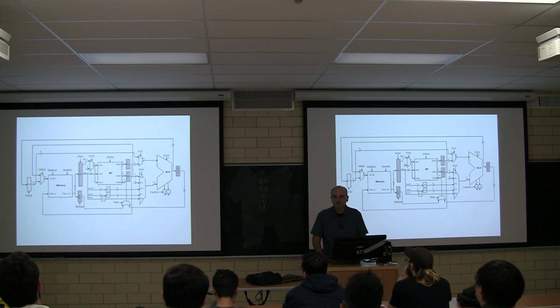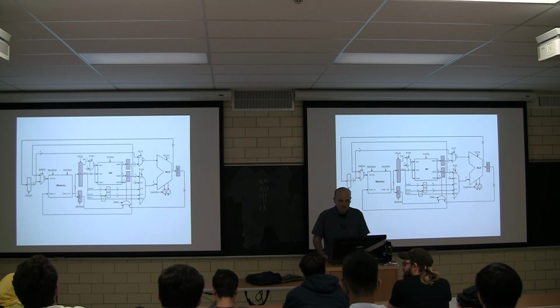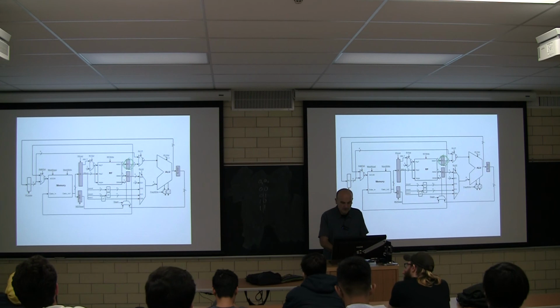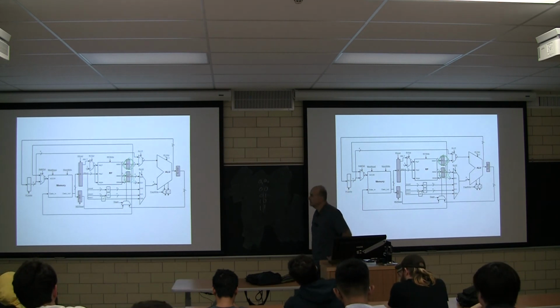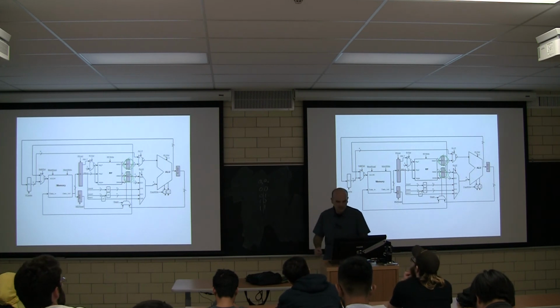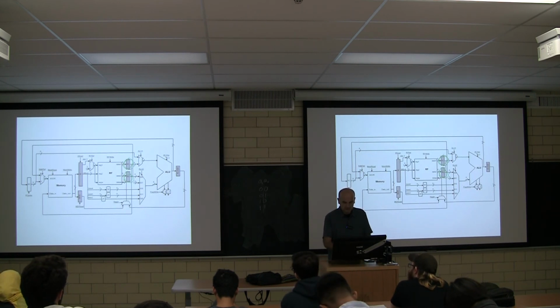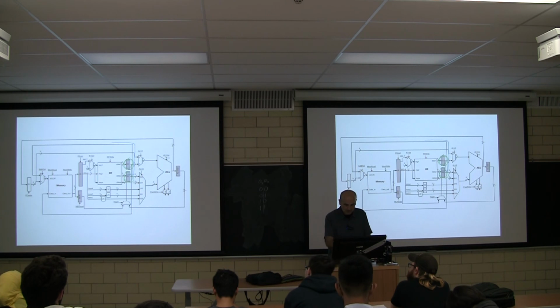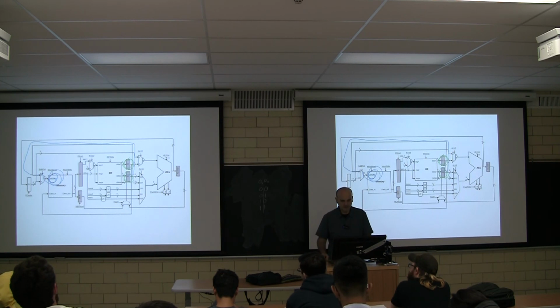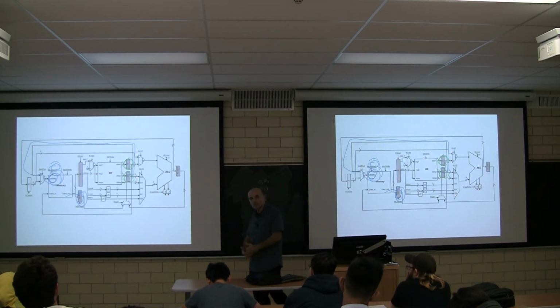Load. Can we do load? Can I spare you the cycle 1, cycle 2? So we're in cycle 2 now, and we read R1 and R2. Okay. Good thing, because now in cycle 3, R2 is useful. R1 is useless for us because this is a load. But in cycle 3, we can go and say, take R2, go through this wire. You see this wonderful wire over here? Go through this multiplexer here and go to the address. Do a memory read, and at the end of the clock cycle, go to the memory data register and write the data from memory into that.